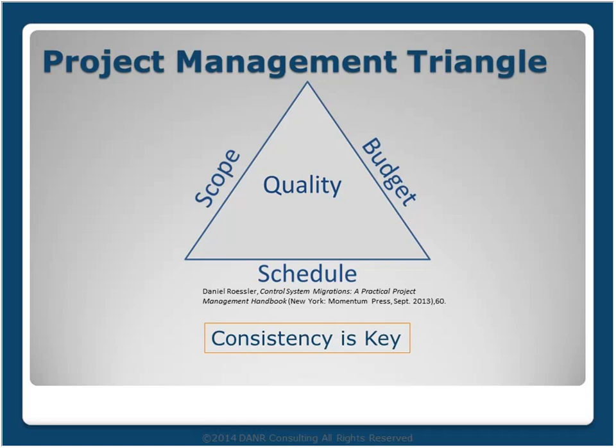For example, if you're building a house and you have a single schedule line item that says complete the foundation, and the duration's 2 months. But then when you start looking at your budget, you build a lot more granularity into it, and you've got a line item for excavation, you've got one for leveling, for purchasing concrete and rebar, for pouring concrete, etc. Then what you've done is you've created an inconsistency between the schedule and the budget. And so as you're spending money doing the items in your budget, you have no way of tracking that against your schedule because you have a single line item.